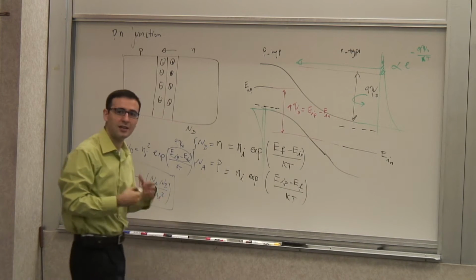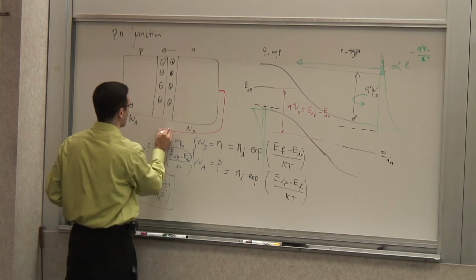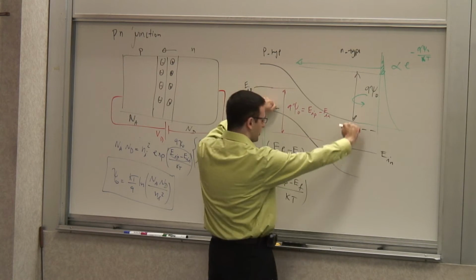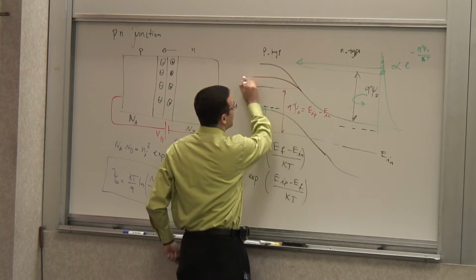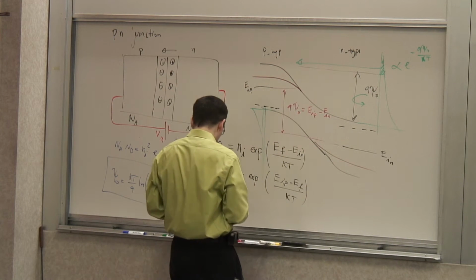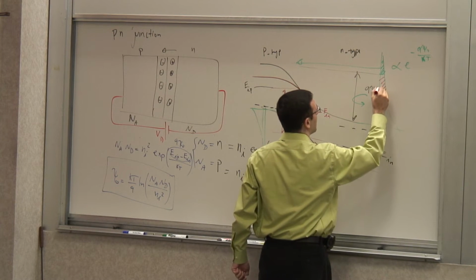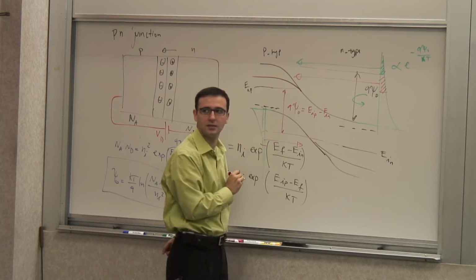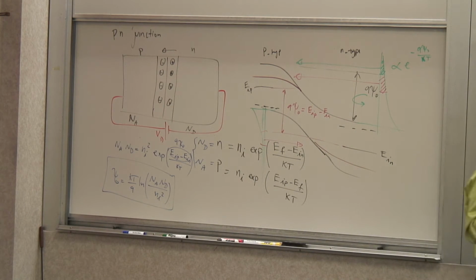Now, when I apply a potential, an external voltage, like a forward bias in this case, Vd, I lower this potential barrier, right? I push it down. So when I push it down, this is what's going to happen. So I lower this potential barrier on this side, lower this one on this side, and what happens is that in addition to those guys who could pass, now a whole new bunch of guys can pass, and these holes can pass across the barrier, because now the barrier is lower, now there are more electrons and holes who have enough thermal energy to cross.